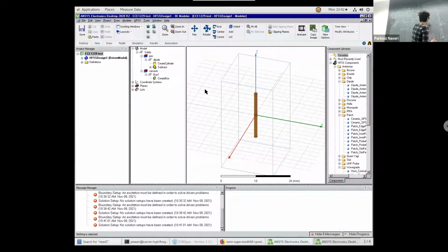And then you can assign Z to this lumped port. I would say it looks like an intrinsic resistance of the source. So I can define it to be 50 ohm, or as I know the Z impedance of the dipole, I can define it 70 ohm, but it doesn't matter. I'll show you. So let's assign a lump port.